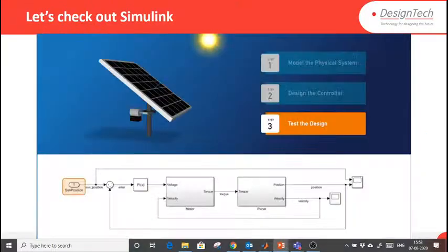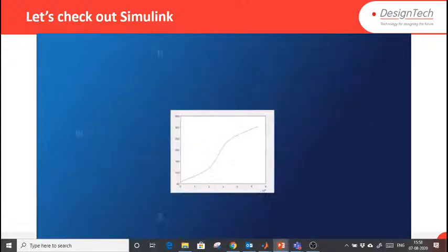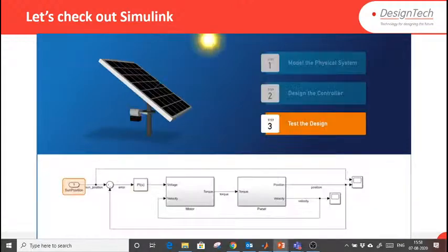So till now what we saw, we designed a panel. To rotate that panel, we designed a motor. To control the error, to minimize the error, we used the PI controller. And again the output was not tuned because there was error. We checked with the input reference and output, right? So for that we used the PID tuner to tune that data, right?